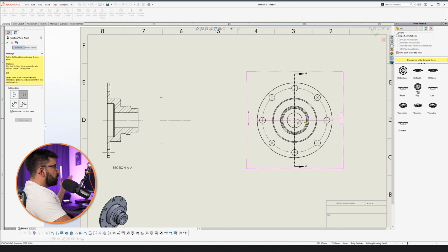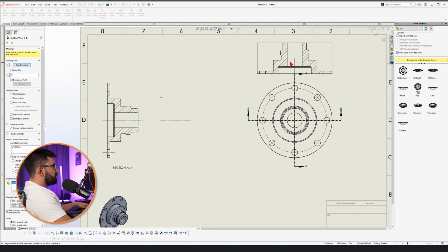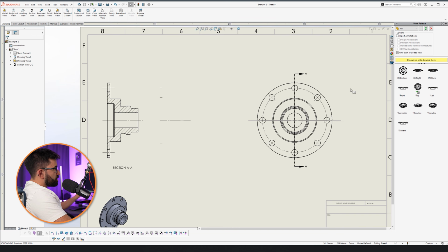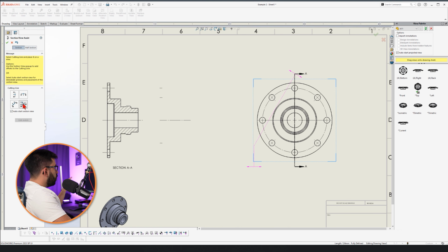Well, the horizontal one is the same. We don't want to reinvent the wheel. I'm just not going to click that. Press escape to get rid of it, but the line for that still remains here. Select it, press delete. Let's just take care of this one. 1, 2, 3. So let's just select the first point here, the second point there, and the third point there.